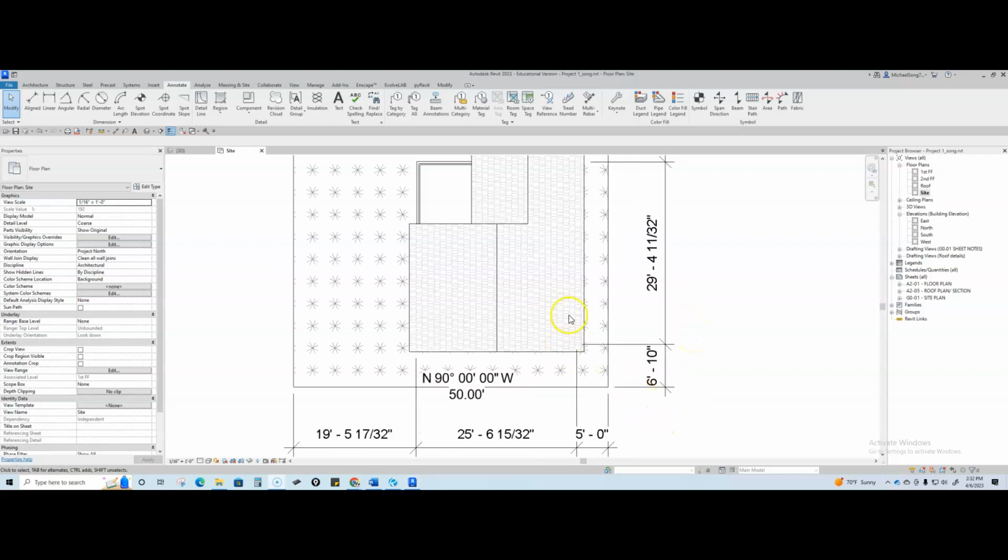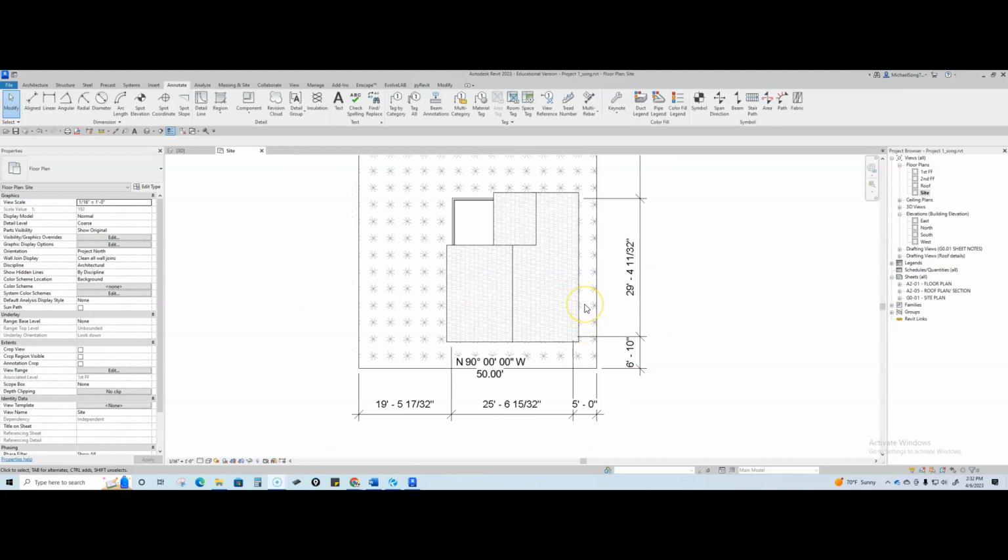And I know that I glanced over these setbacks here, but that is really, really important when you guys are laying out and creating any project. Every project has a setback requirement. And the setback simply means that from the property line, you have to put any kind of structure set back a certain distance from the property.